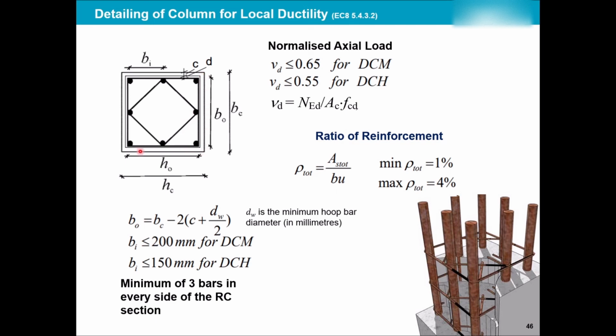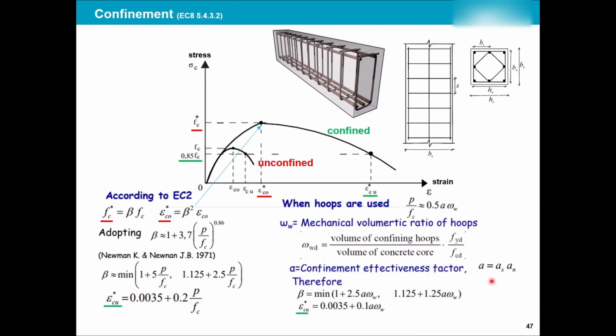Remember, the concrete on the sides is called the cover. The concrete which is inside these hoops or stirrups or the shear reinforcement or the transverse reinforcement is the core concrete, or the confined concrete. The concrete around it is the cover, or the unconfined concrete, which is not hugged. You see, any concrete in the middle of this hoop will be confined, as someone is hugging it. Any concrete outside of it is exposed. And if an earthquake happens, the cracks usually happen in the covers while the core stays safe.